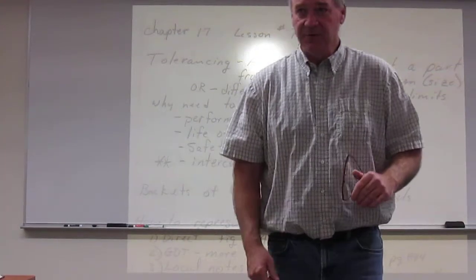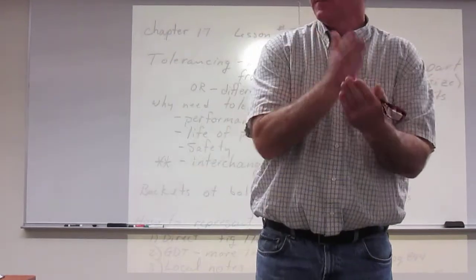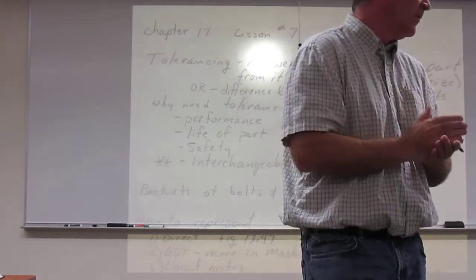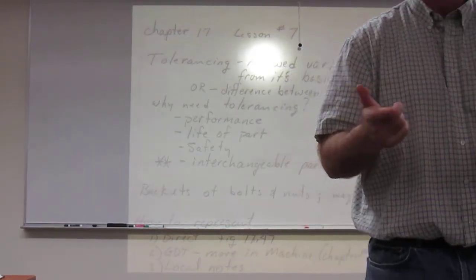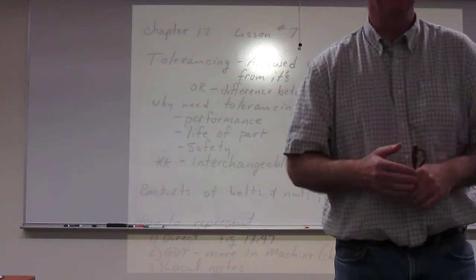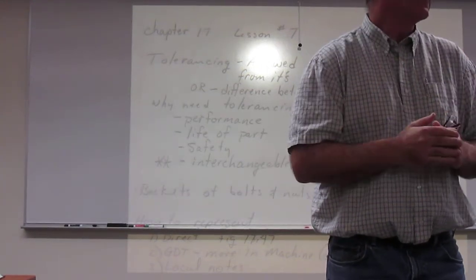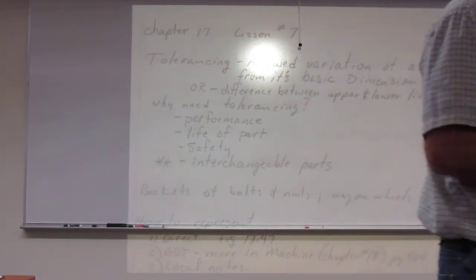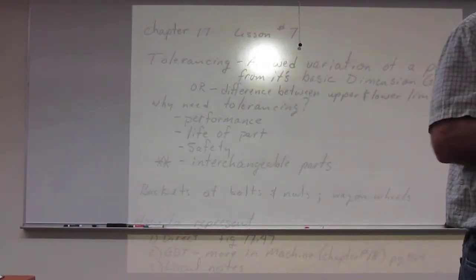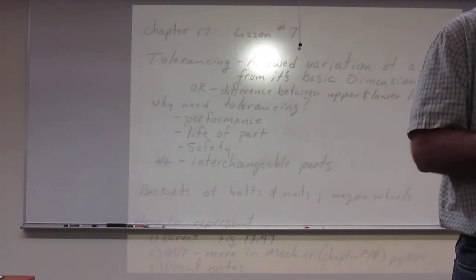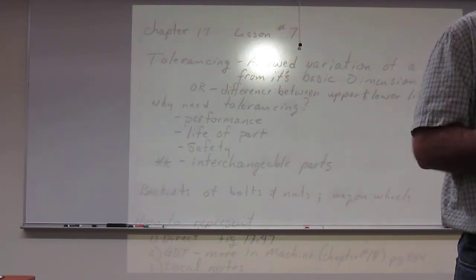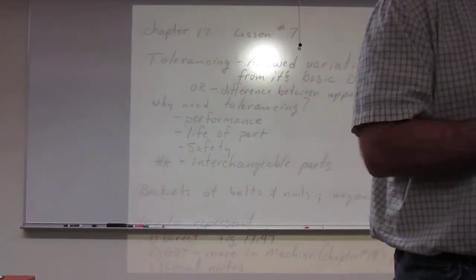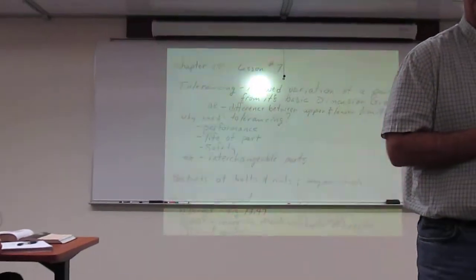Right now you're doing a general tolerance where you say all dimensions plus or minus 0.02 inches in your general notes, which applies to the drawing as a whole, or all dimensions plus or minus 1 millimeter. Those apply to every object on there, and we don't really know if our parts are mating with other parts. We're doing them as standalone. But in essence, tolerancing is all about how a part performs with the parts that are mating with it. That's what it's really meant for.